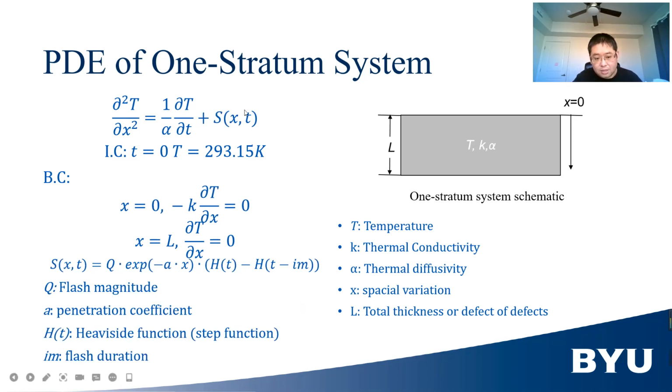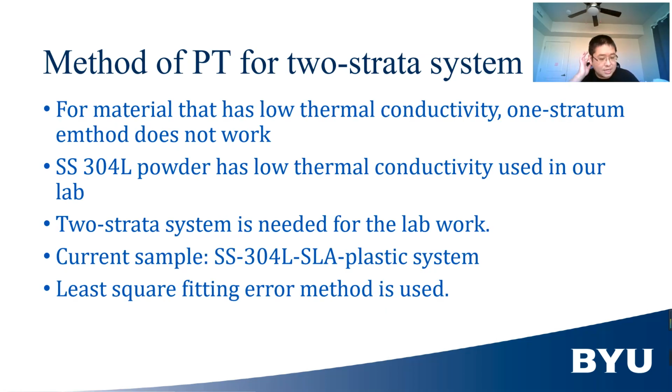Now let's see what we can do to the PDE system. I add a free term. This free term expresses the penetration depth and the flash duration, which means that we can add much more factors if we want, such as convection or some other reflection from the environment. But this method has a problem, because we are studying samples that have very low thermal conductivity. Even if air is beneath the sample, we cannot consider the sample as totally insulated.